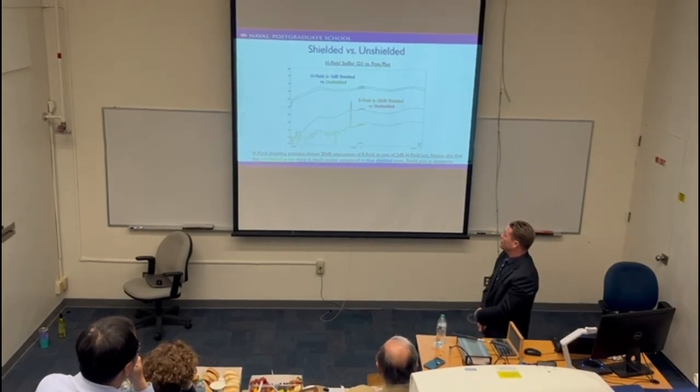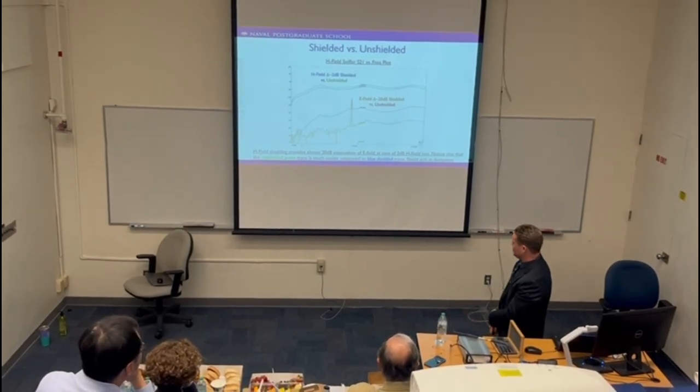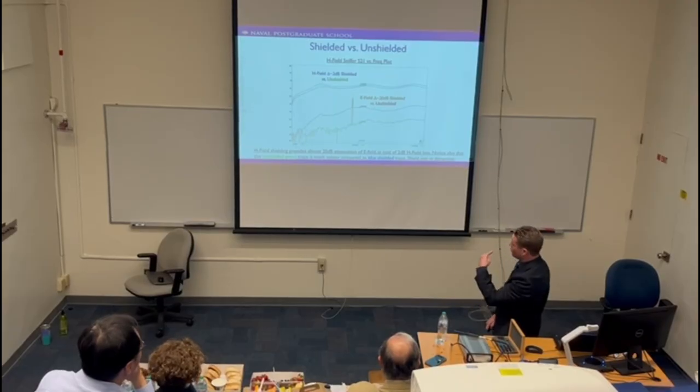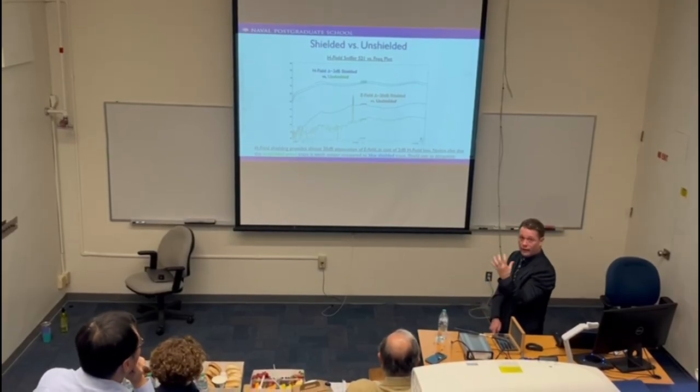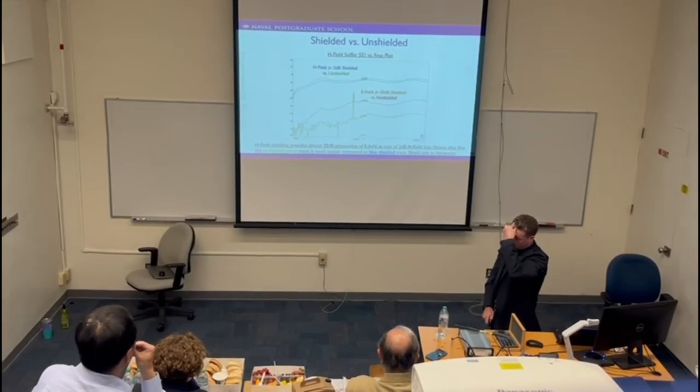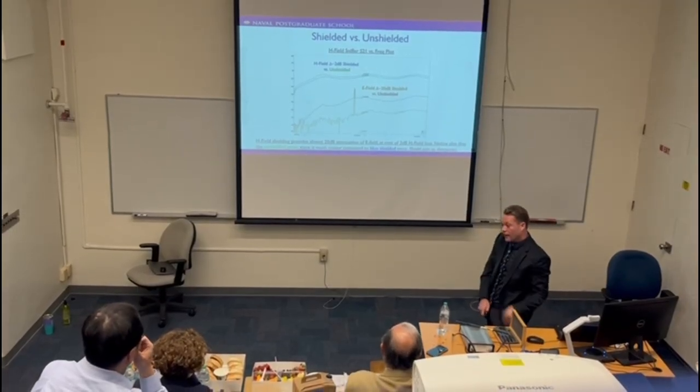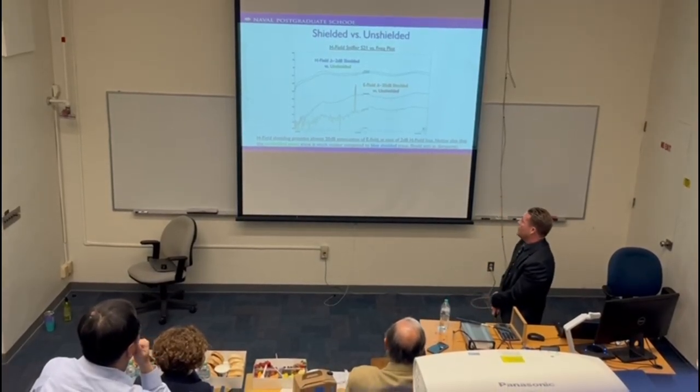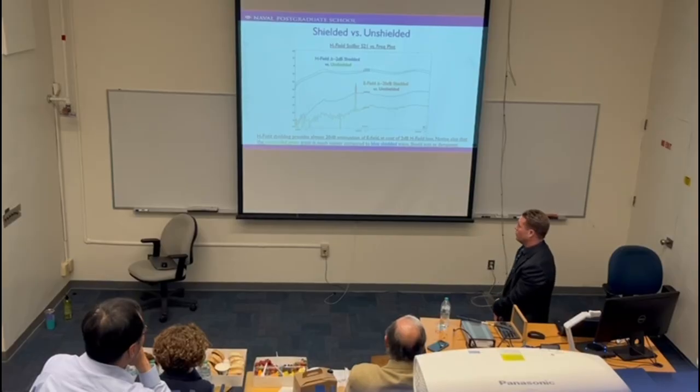You do lose about, say, 2 dB in the shielded H field. However, I lose 20 dB of E field. Remember, that was the whole decoupling purpose. I was trying to decouple the E field from the H field so that I got more differential mode type coupling. And you can see here, measurements show very effective.